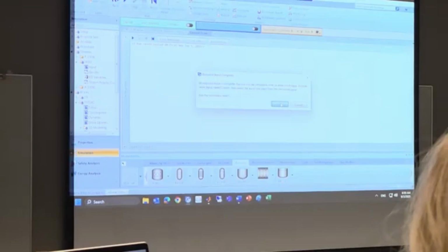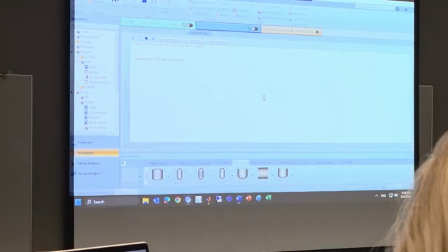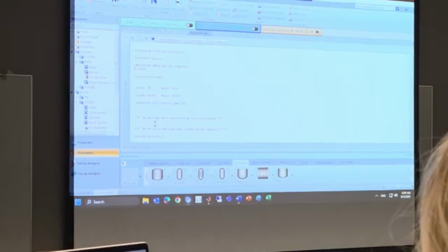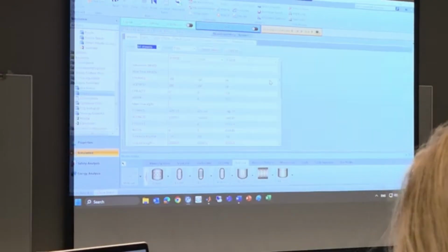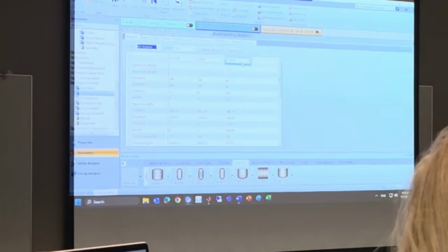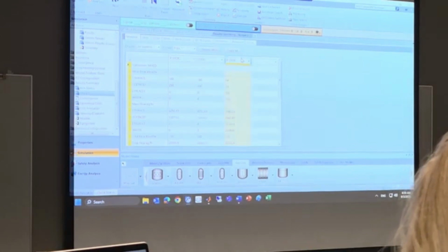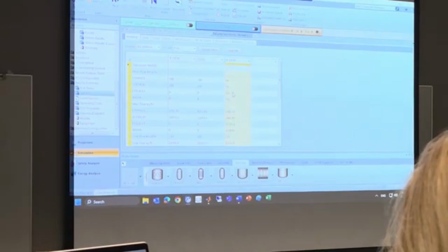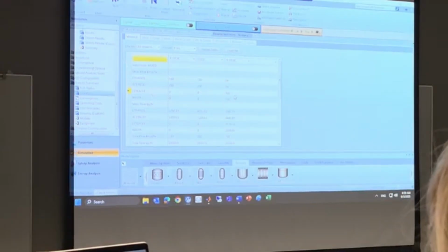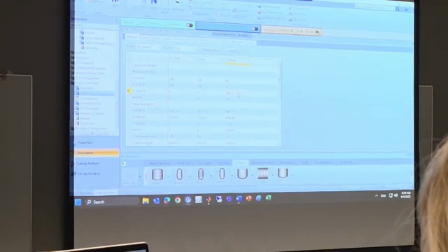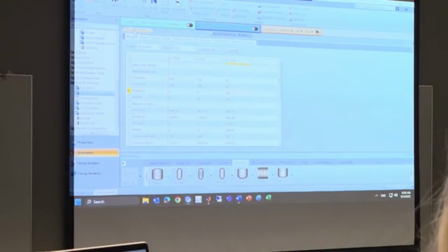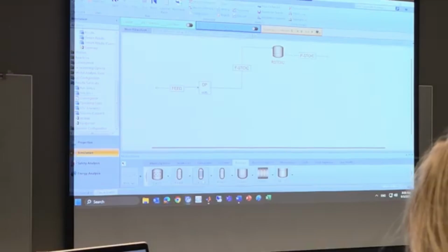Let's look at our simulation results. No worry, no error. Then we can go to the sim summary because we are interested in how much ethyl acetate is produced from this reaction. So I can look at it. This cell produced 126 kilomole per hour of ethyl acetate. Easy? Alright, let's go quickly then.